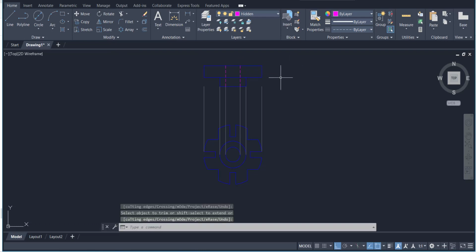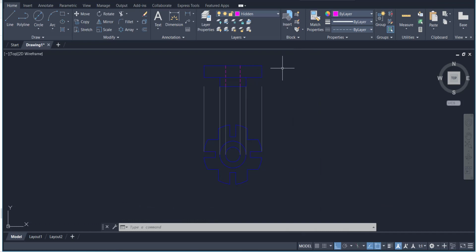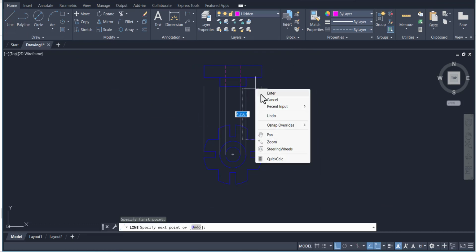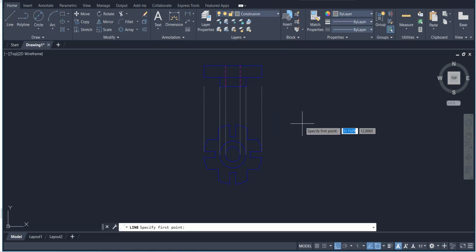Okay, so next what we see on the top view. If we see this object from the top view, these edges will be showing here, and this edge from this point will be hidden here. So first I am going to track this point, make sure you are in the construction. So when we shift the view, we draw a line from every point.